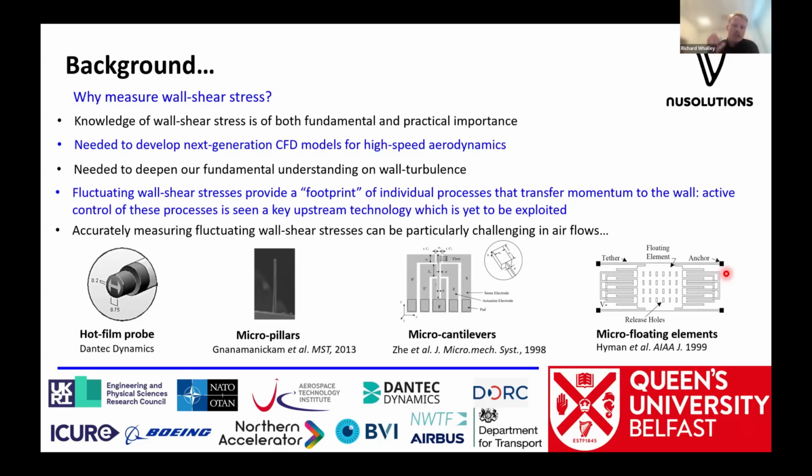And so that's one aspect in terms of the fundamental knowledge, but also in terms of the CFD, so computational fluid dynamics. If you want to try and develop some new models for high-speed aerodynamics, for designs of, say, new aircraft, what's vitally important is to know what's going on along the boundary of those simulations, which is where the wall shear stress comes in. And it's very difficult to take these measurements of the wall shear stress in these types of high-speed flows.